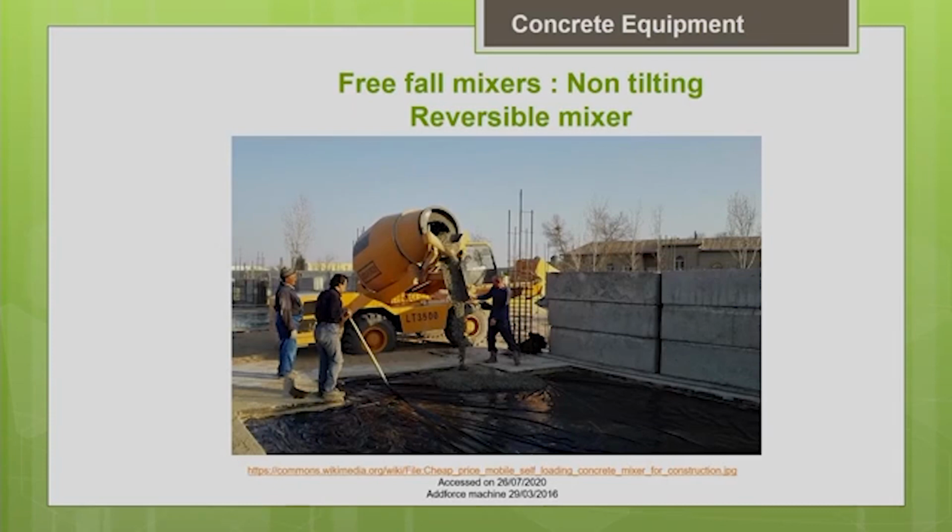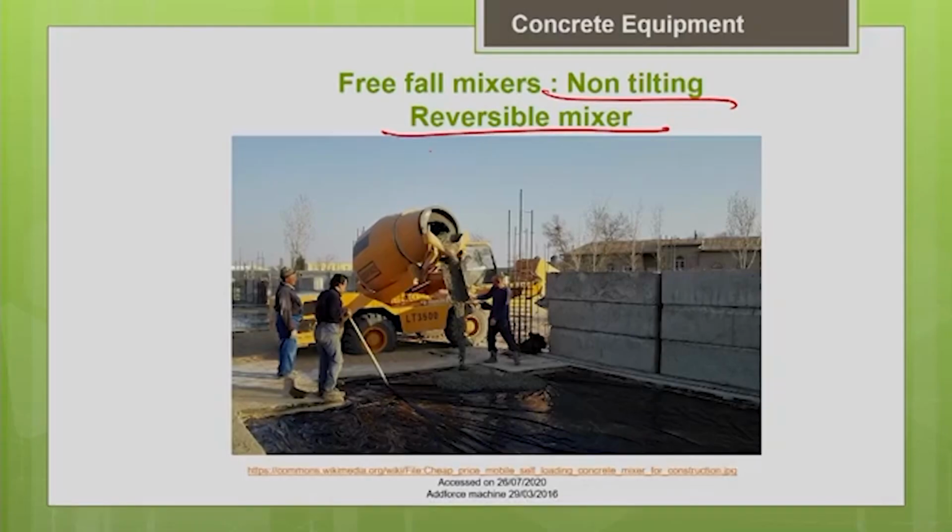So, this is also one more configuration of non-tilting reversible mixer. Here you can see there is only one opening. You can feed in the material with the tilting hopper and you can discharge the material outside by just rotating it in the opposite direction. So these are also reversible mixers.